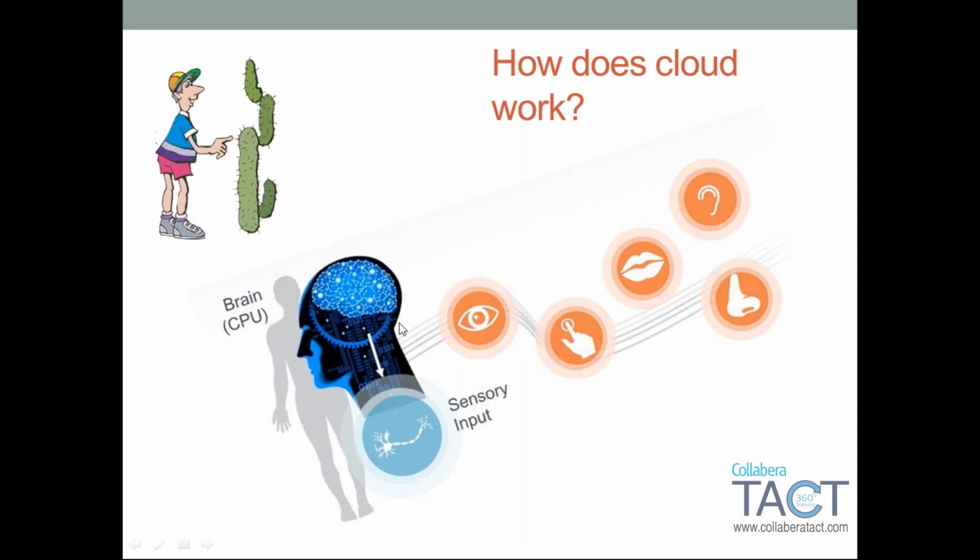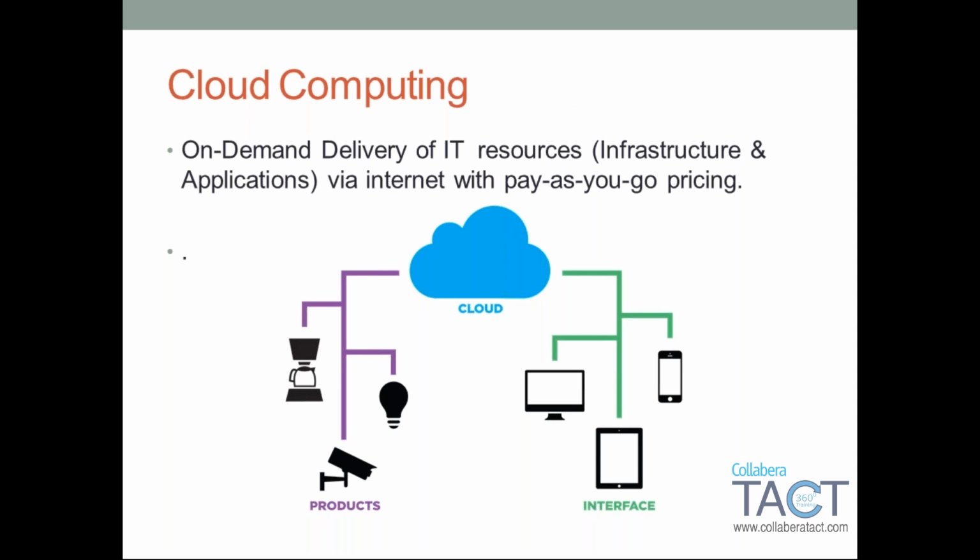The second benefit of using the cloud is that putting computing load on our device is going to consume more power, because the power consumed by a processor is proportional to its operating frequency. So if you put more computing load on our end devices, it is going to reduce the battery lifetime. The strategy, therefore, is to put less computing load on the end devices and more on the cloud. Only sensing and actuation is managed by our device, while computing is done on the cloud.